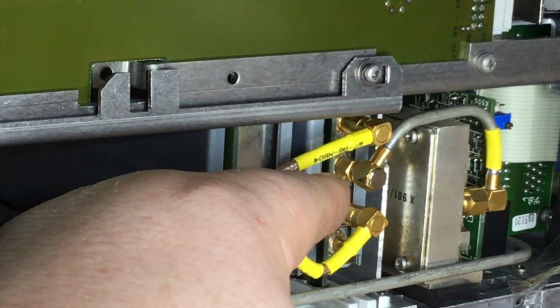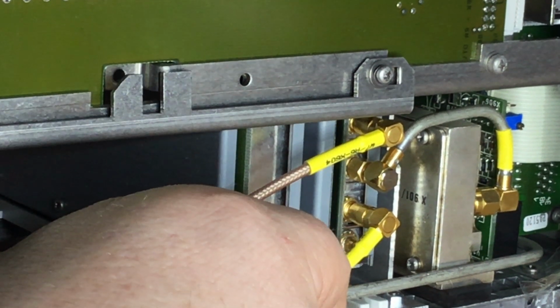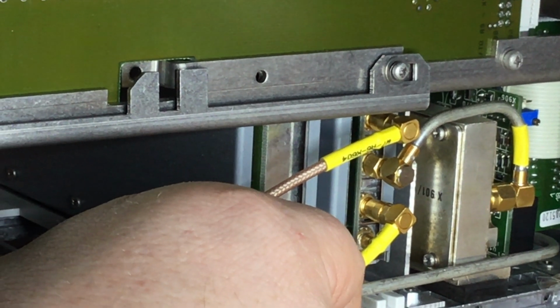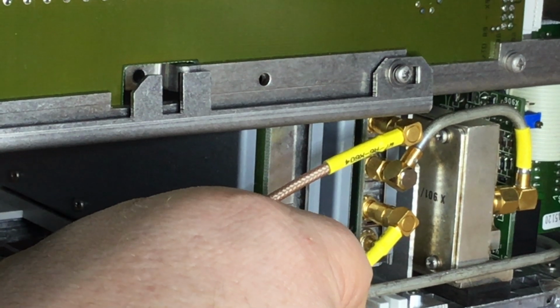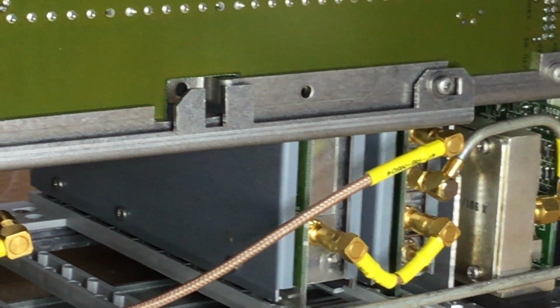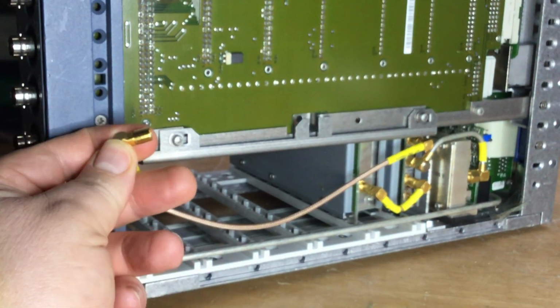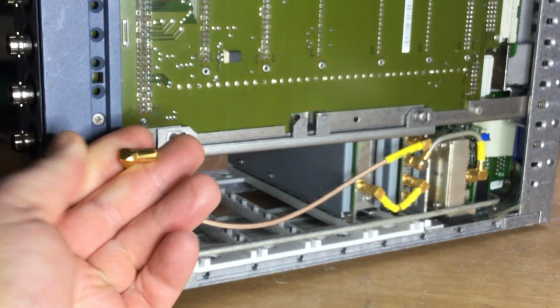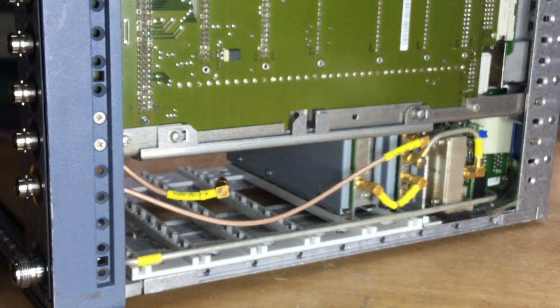So an SMC is very similar to an SMB, except it has a screw thread at the very bottom of the push part of the action when you push the socket on. So SMBs are just push fit, obviously, because they've got a dedicated collar which just pushes on and then clicks on. So that's the difference between an SMB and an SMC.